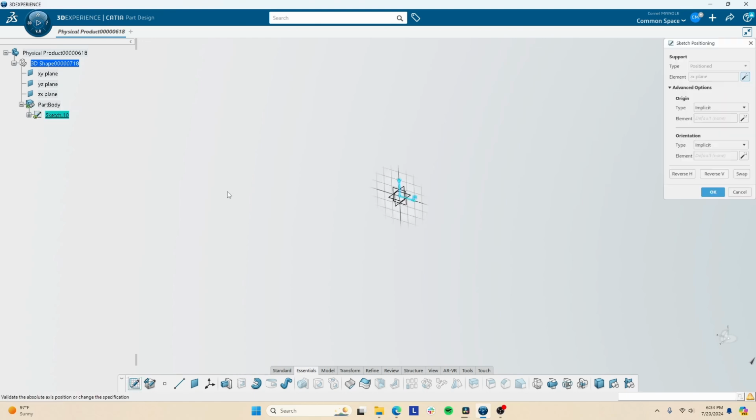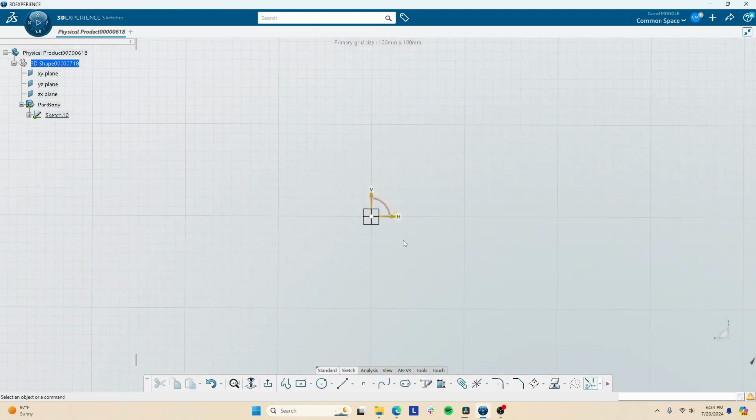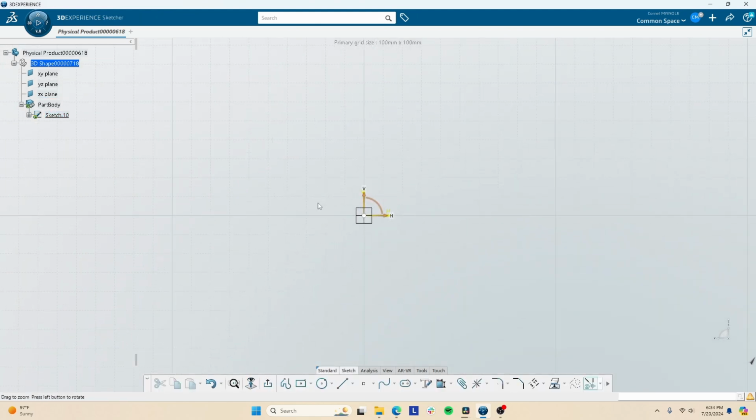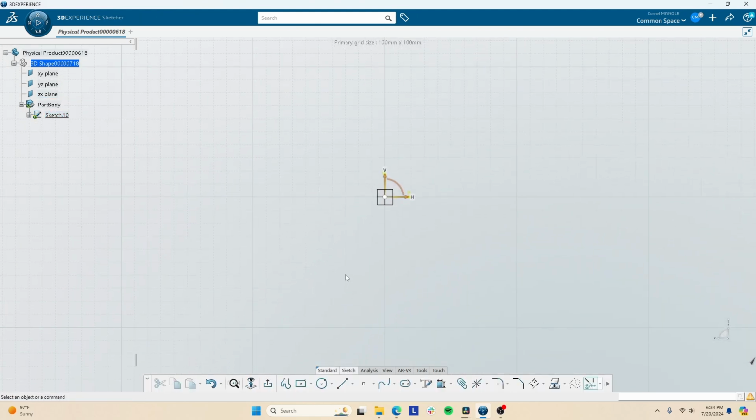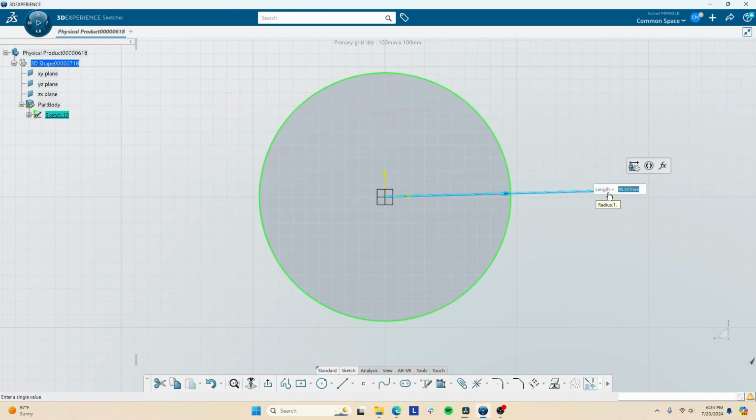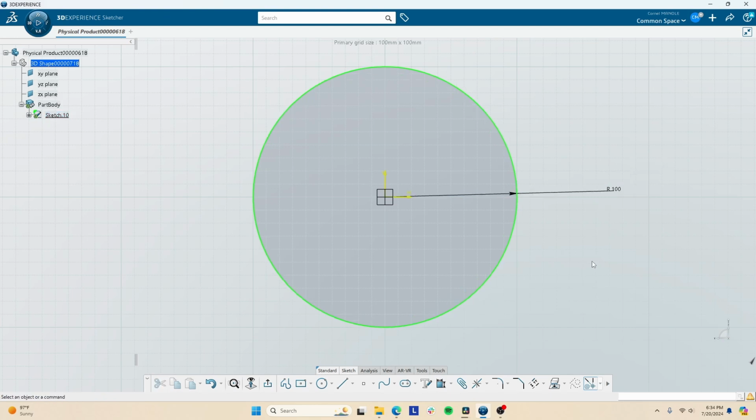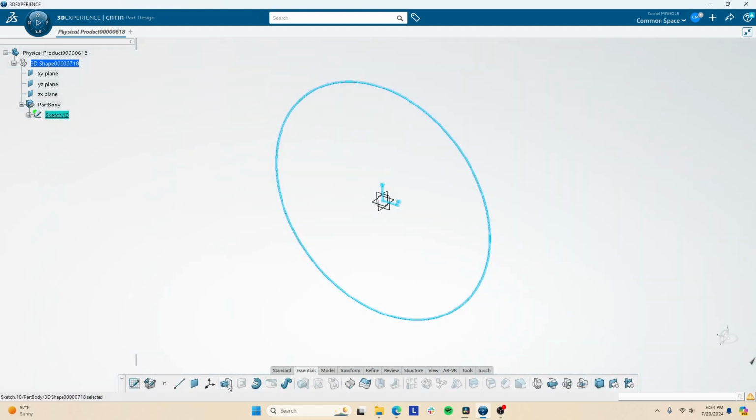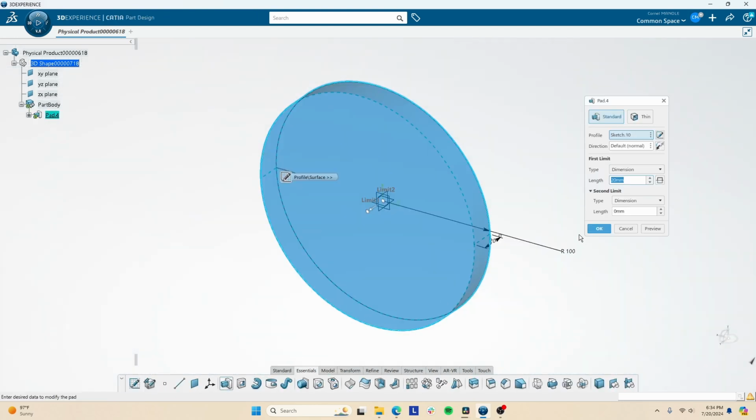So you should have seen the Sketcher tutorial beforehand or just know about it. Or maybe you could just intuit it because it's pretty straightforward. I'll create a profile, constrain it, measure it, and we can create a pad from here. Some things that we can do with the pad.